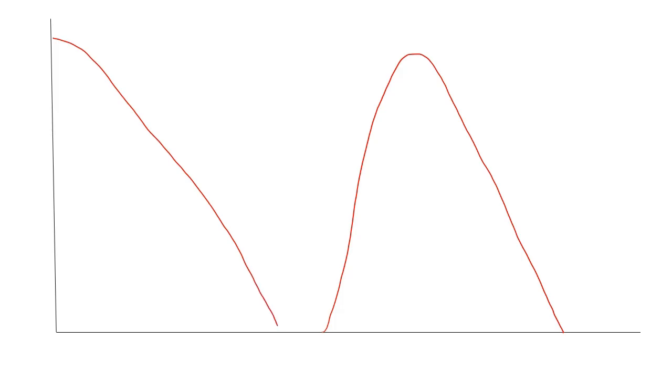Now, there is another important factor with respect to the digital transmitter, that is the update rate or the sampling rate. The digital transmitter sends a signal whenever there is an update or a sample of the signal. In the case of the anti-surge system, the flow rapidly decreases, right? And in the phenomenon of multiple surges, the flow signal is reversed multiple times.